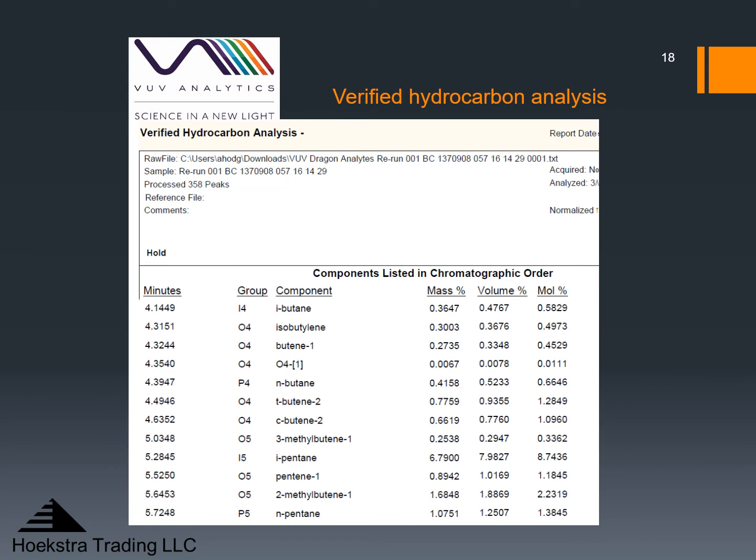Here is an excerpt from the VUV Verified Hydrocarbon Analysis Report giving concentrations of individual hydrocarbons at the molecular level in the Dragon software format familiar to those who do detailed hydrocarbon analysis. The VUV Verified Hydrocarbon Analysis quantified 358 peaks in this FCC gasoline, and our performance curve spreadsheet model uses this full molecular detail as input.